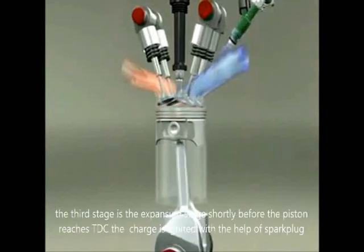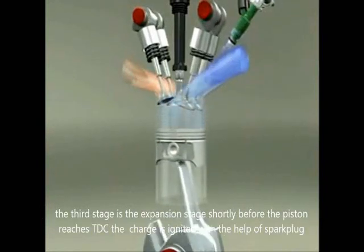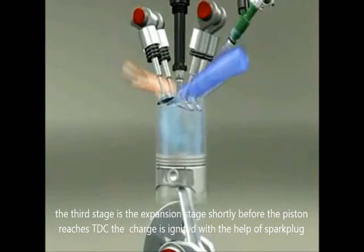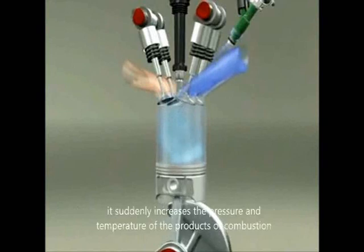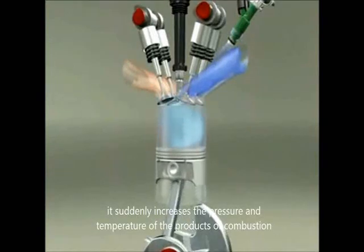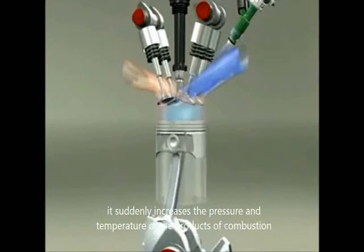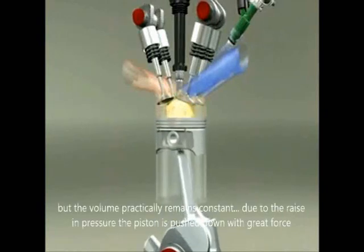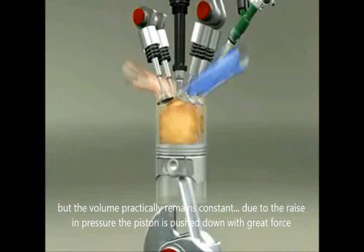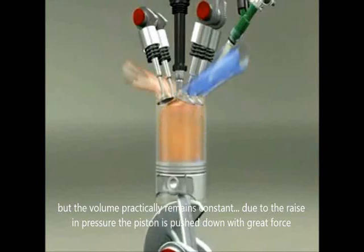The third stage is the expansion stage. Shortly before the piston reaches the TDC, the charge is ignited with the help of the spark plug. It suddenly increases the pressure and temperature of the products of combustion, but the volume practically remains constant. Due to the rise in pressure, the piston is pushed downwards with a great force.